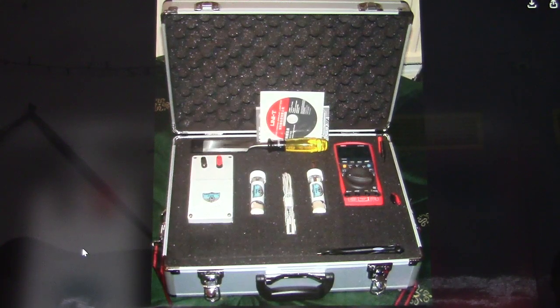The equilibrium of the cell. When placed on the ground with electrolyte, the Alexander cell establishes a dynamic equilibrium. The base electrodes behave equally due to identical preparation, while the top electrodes create a potential difference that drives corrosion current. When connected to a pipeline under the cathodic protection system, the system changes.